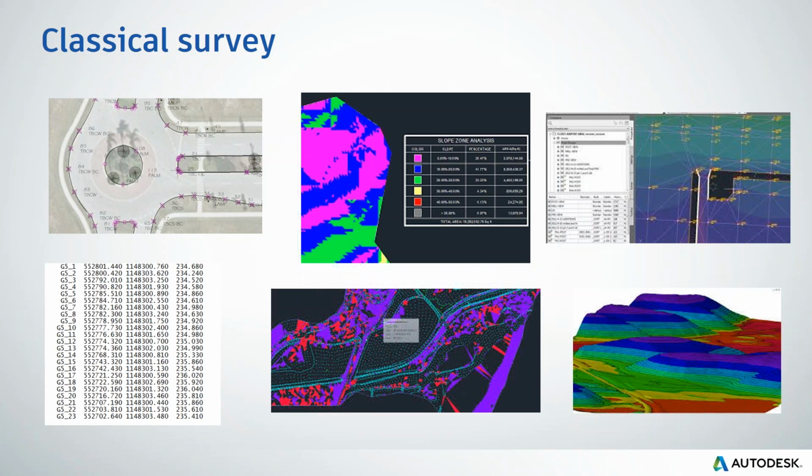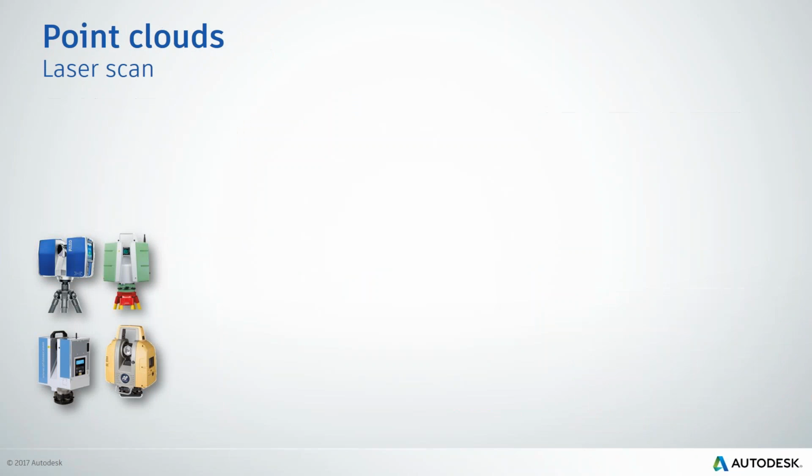So we can produce a lot of different analyses like slopes to see if there are some mistakes or what is the current behavior, because it will also set up a good stage for road rehabilitation if I'm supposed to change crossfall because of the water or because of the design speed, etc. So there are a lot of examples why I want to conduct a very precise, and in fact also colorful, but not only colorful, very important existing ground analysis.